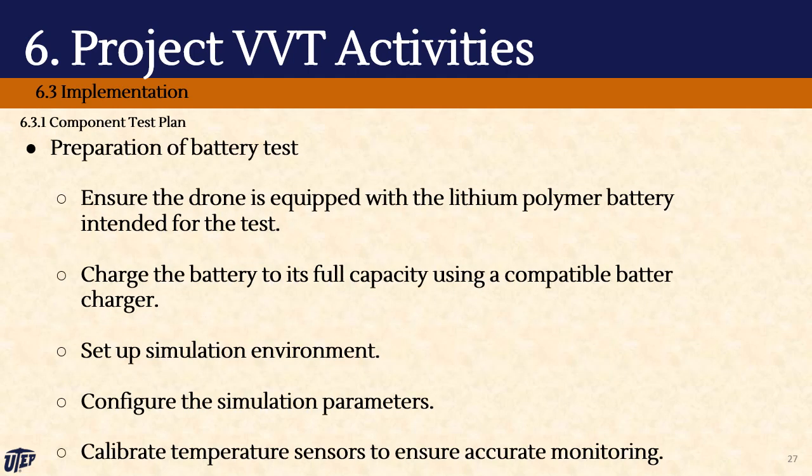Before the testing begins, there needs to be strict preparation for the test to ensure that all the data is collected the same way and is standardized in the output. It is vital to ensure that the lithium polymer battery has passed a quality test and is not defective. This is so the team gets an accurate output after the tests are conducted. The battery will be charged to its full recommended capacity before every test by using a compatible charger to ensure the battery does not degrade more than it should.